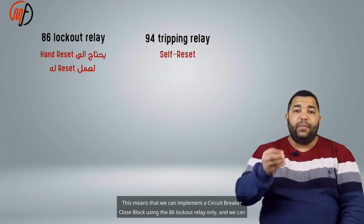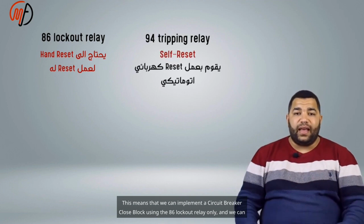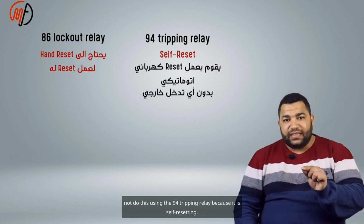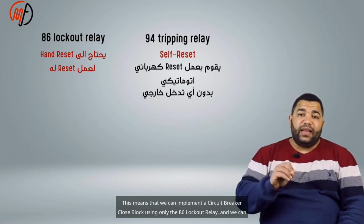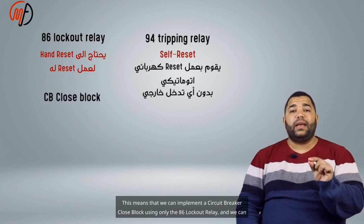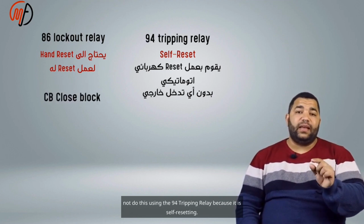This means that we can implement a circuit breaker close block using the 86 lockout relay only, and we cannot do this using the 94 tripping relay because it is self-resetting. This ensures that its operation does not conflict with the operation of the autocloser relay.